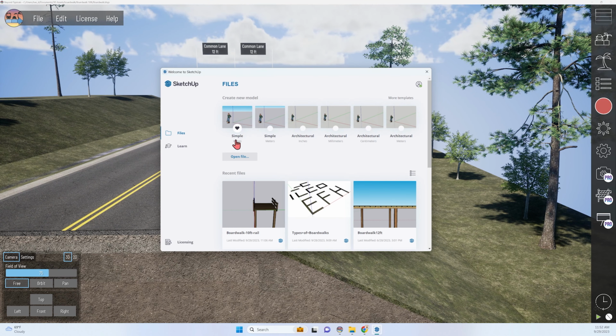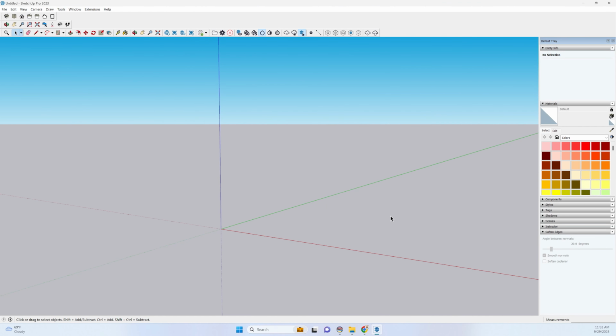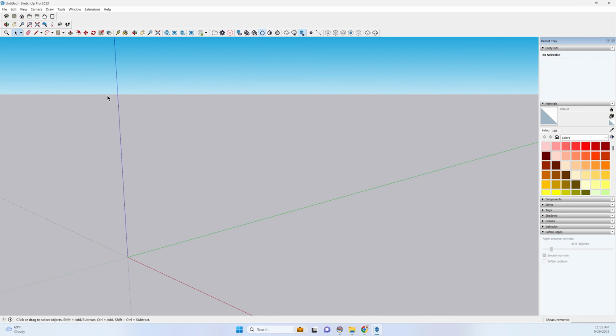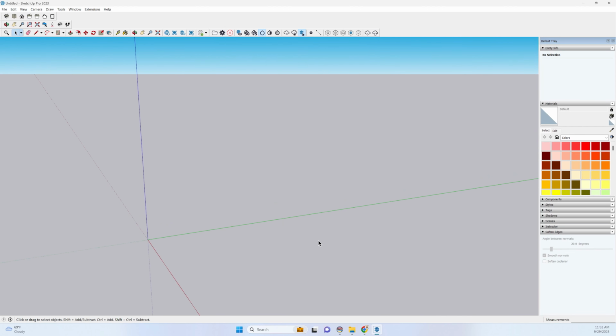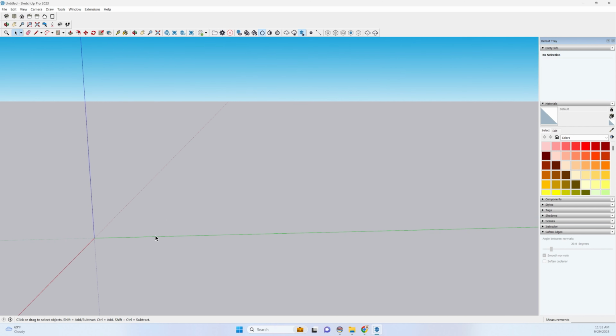And I'm going to draw in the inches model because that's how I'm going to enter in the different dimensions of various elements in SketchUp. You could draw in other units, but I want to highlight that when we go to export this model, we'll export it with a unit of centimeters, so it will convert and scale correctly when importing that file into Beyond Typicals. As I've mentioned in other videos, we recommend that aligning your green axis as the front edge of whatever you're modeling is best to bring an asset into Beyond Typicals, so I've rotated my view accordingly.